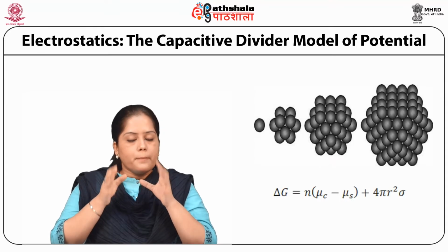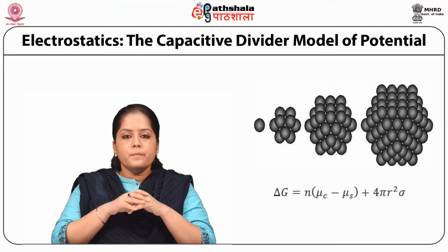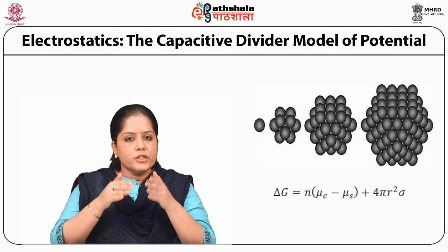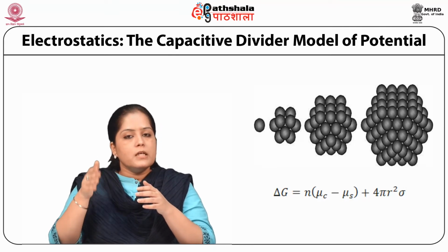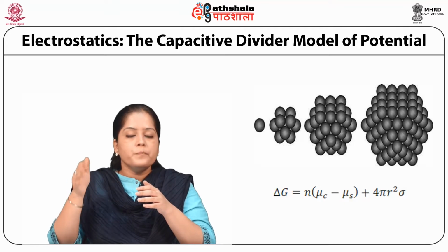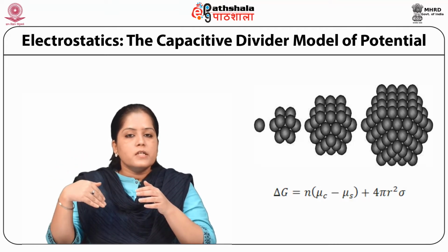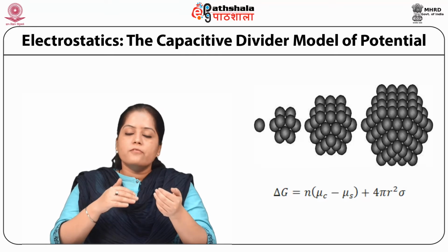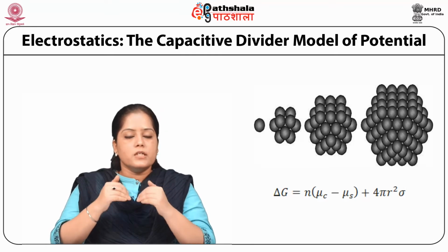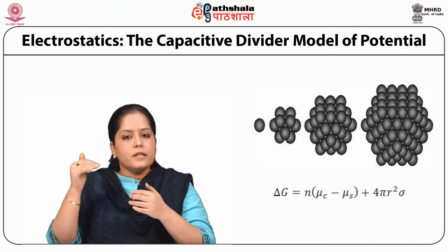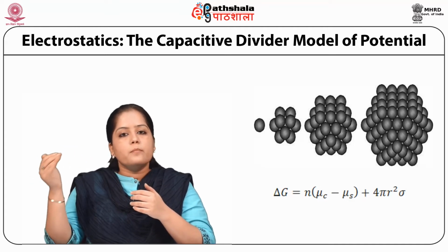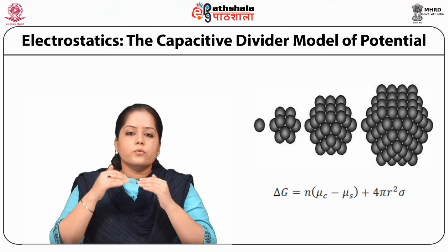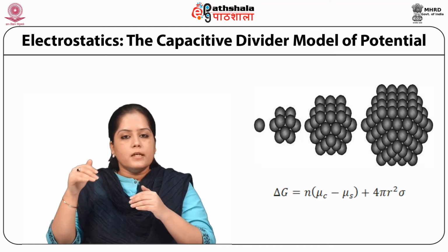So the expression for the quantum capacitance is given by n equal to the integral from minus infinity to plus infinity of G(E) multiplied by f(E minus EF) dE, equal to the integral from minus infinity to EF of G(E) dE, where delta EF equals delta N divided by G(EF), multiplied by delta EF equals q squared by CQ multiplied by delta N, where CQ equals q squared multiplied by G(EF).